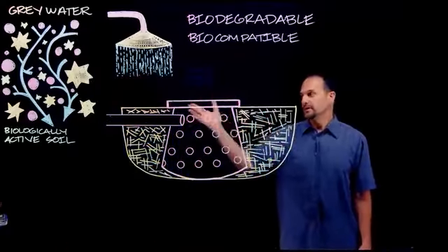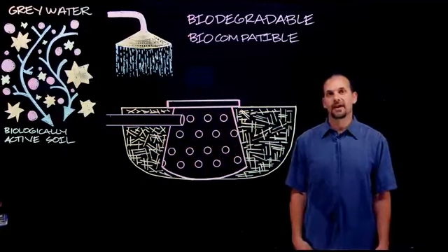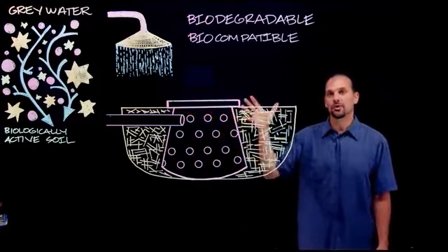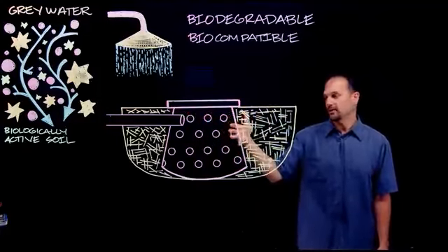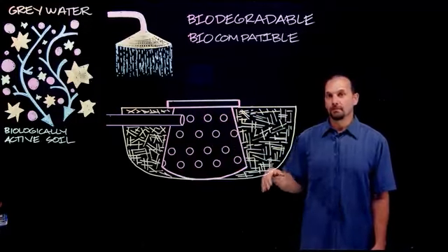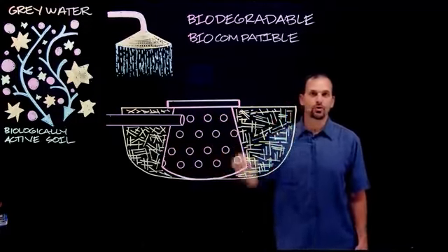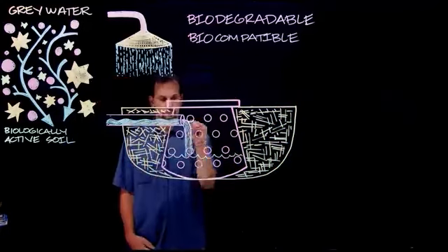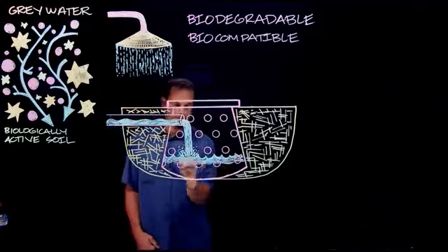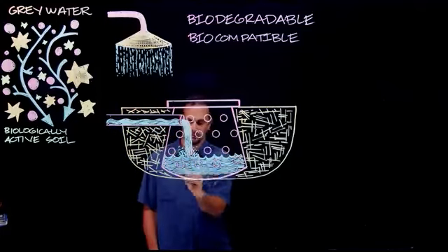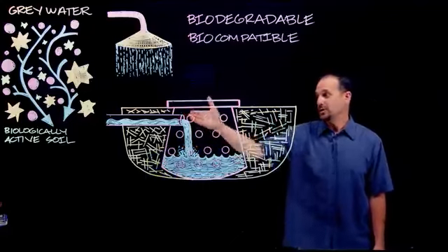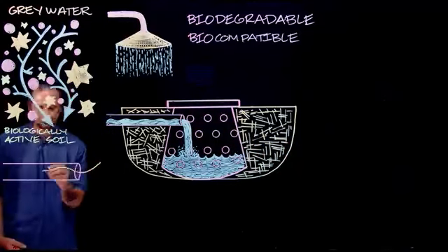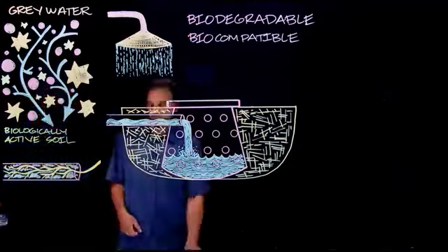Now, the gray water is split from its source into various outlet points, and each outlet pipe flows into a bucket with the bottom cut out and holes drilled into it. So the bucket is surrounded by wood chips or other coarse mulch and has a tile on top. So all this is happening underground. The water spills out of the pipe and has a free fall to the bottom of the bucket. So there's no contact between the pipe and the soil. This is super important because one of the main risks for your system is having roots clog your pipe up.